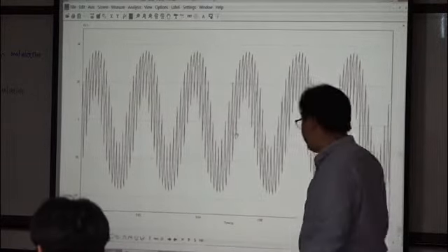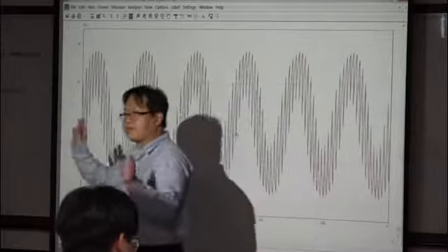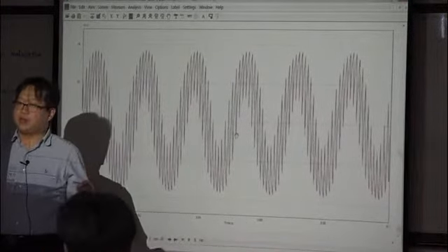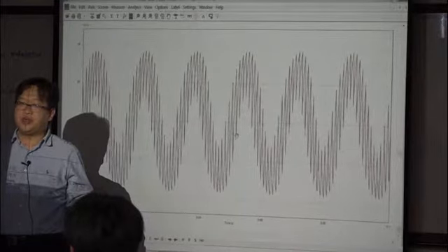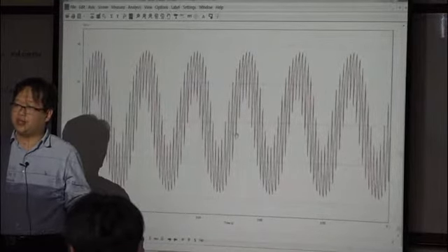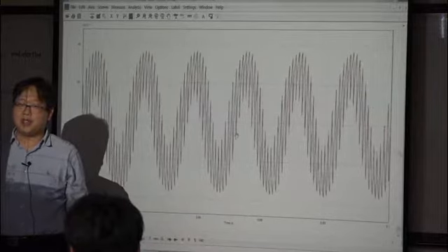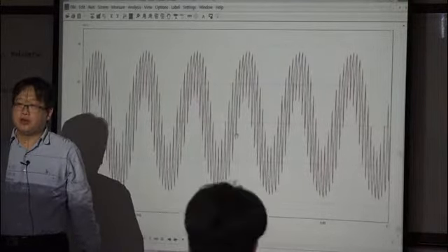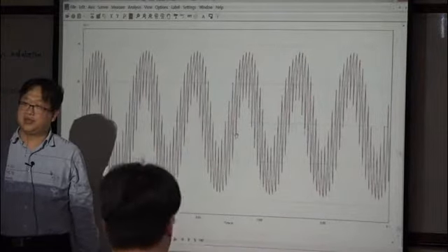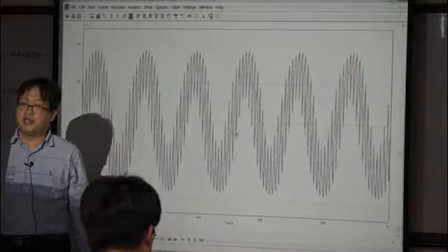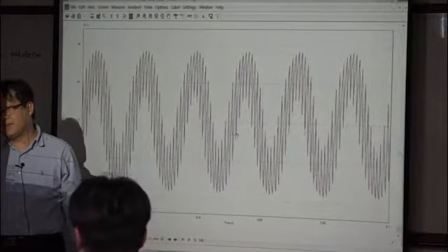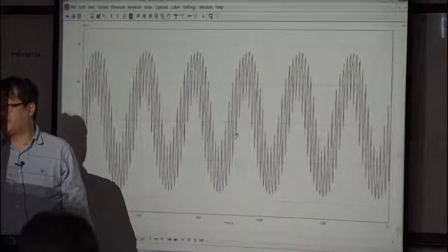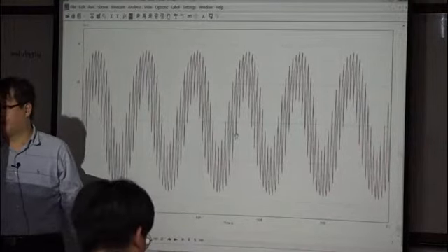And also, think about it. Here, I told you your reference voltage peak is 50 multiplied by square root 2, right? Then its RMS value is 50 volt. Then what is the resistance of your load? Your resistance is 2.5, right? Then what would be the RMS current passing through the resistor in your inverter?